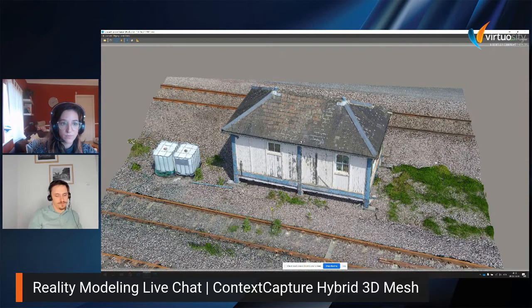Of course, we have to follow some rules when preparing the point cloud, because as we know, they tend to be really huge data. So we have to compress it a little bit. We have to follow some rules in terms of format, so E57 to store information about the normals, coming from the position of the scanner or from the trajectory, if we are talking about mobile laser scanning.